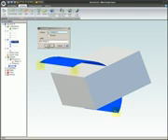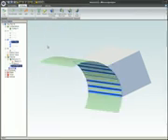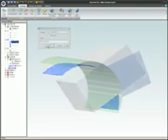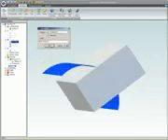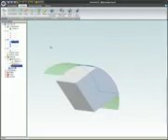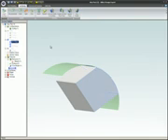Notice the small arrows near the corners of the surface. These arrows indicate the section of the model that will be removed. When the OK button is clicked, the indicated portion is removed. If the Reverse box is checked, the opposite portion of the part will be removed. A Trim Model object has been added to the list of items in the Design Explorer.